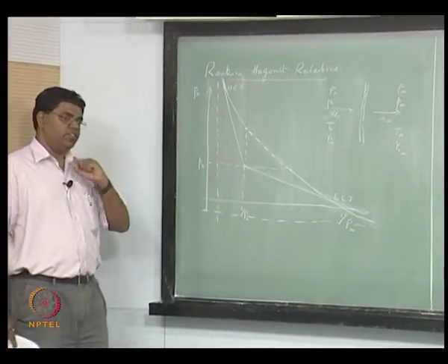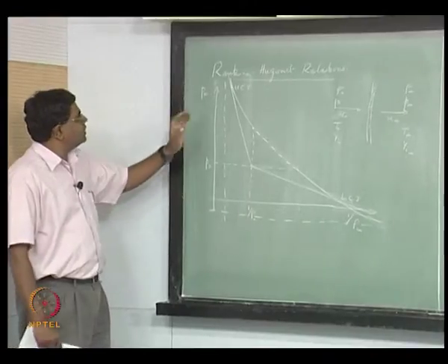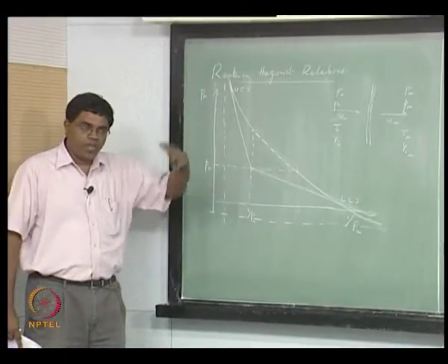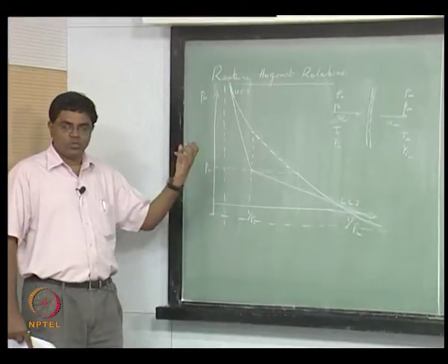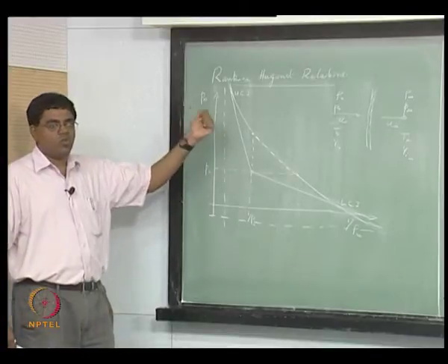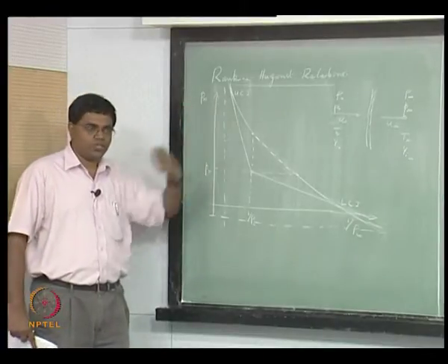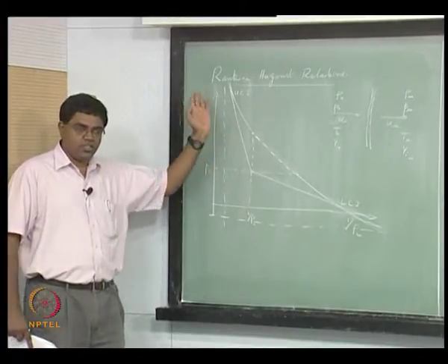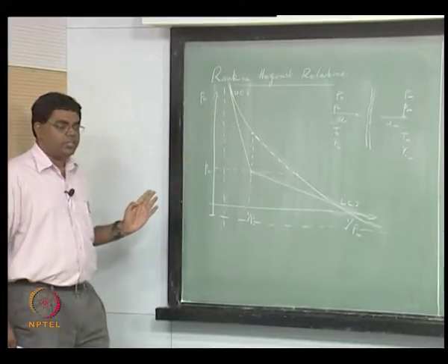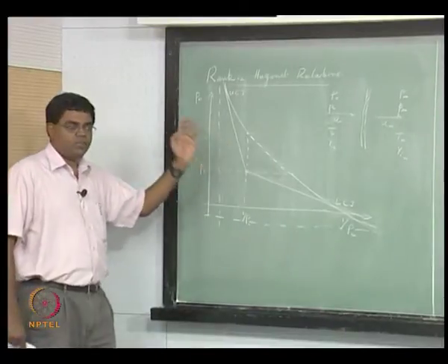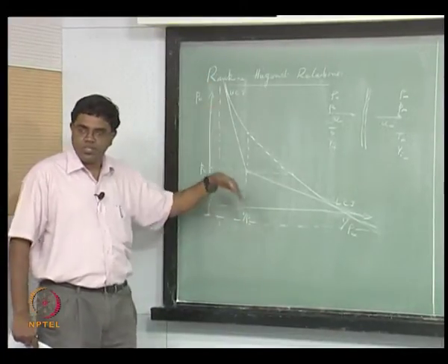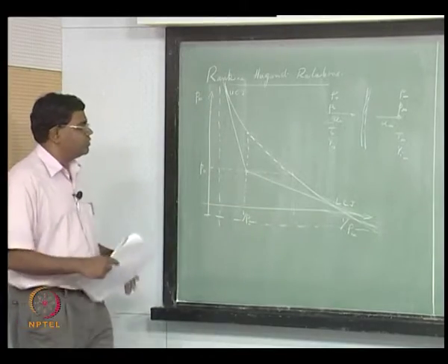So if you solve for P infinity and 1 over rho infinity together with these two equations, you should get a pair of P infinity and 1 over rho infinity that satisfies both equations, and that means it's a point where both of them intersect, right. But in addition to that, at the CJ points we also have to match the slopes, because the Rayleigh line is tangential to the Hugoniot curve, right.